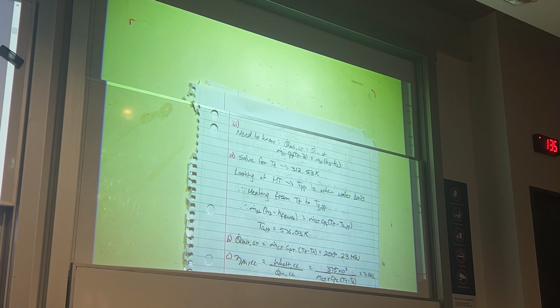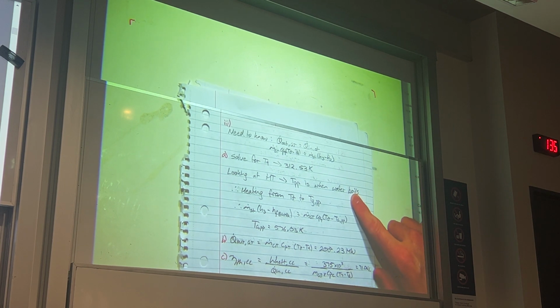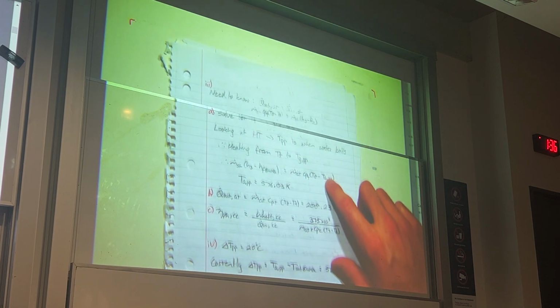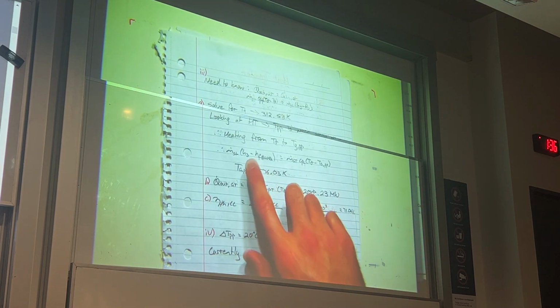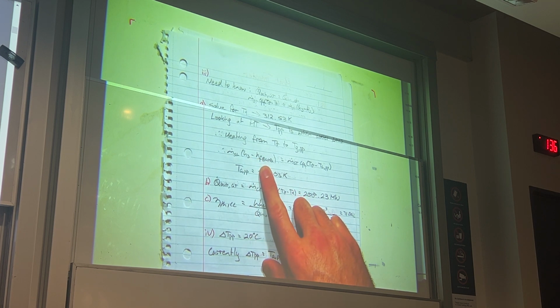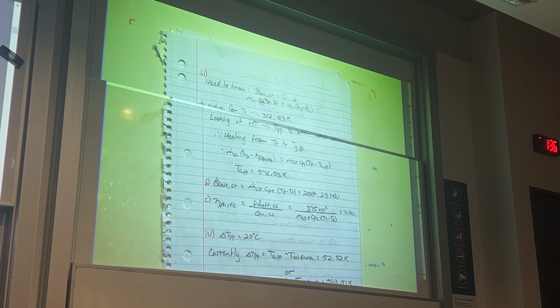And then this is what I was commenting on before. When we switch to looking at the temperature at the pinch point, looking at a heat transfer diagram, it corresponds to when our water gets to boil. So from that, we can create this relation. We're going to go H3 minus HF at 4 MPa, because we've raised the pressure of our water to 4 MPa, and then we're looking at the energy transfer specifically from when it begins to boil.